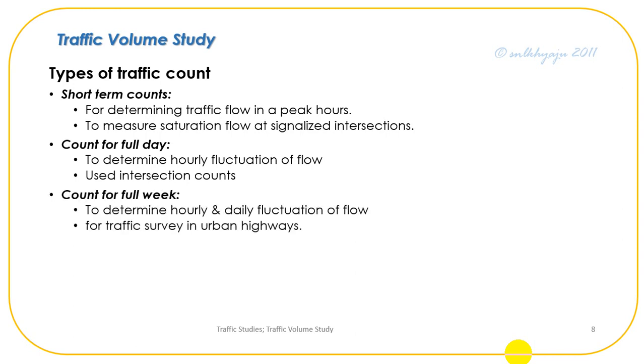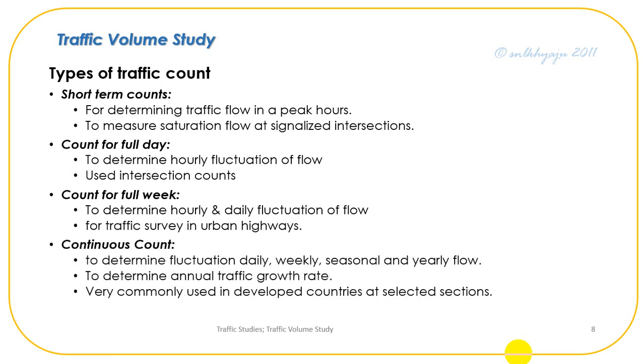Count for a full week to determine hourly and daily fluctuation of flow for traffic survey in urban highways. Continuous count to determine the daily, weekly, seasonal and yearly fluctuation of flow. To determine annual traffic growth rate, very commonly used in developed countries at selected sections.